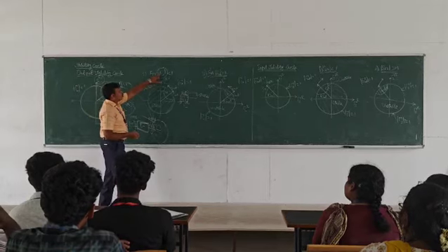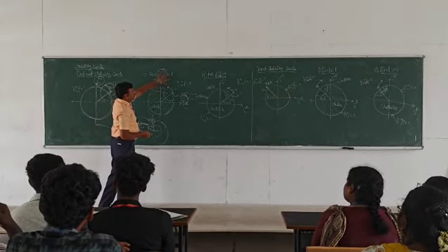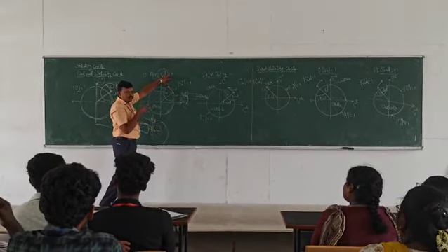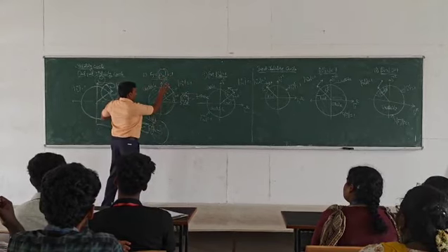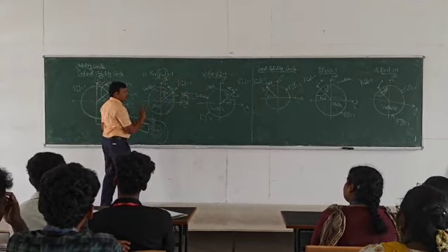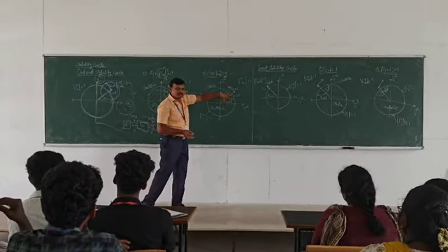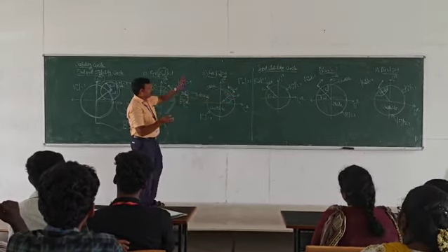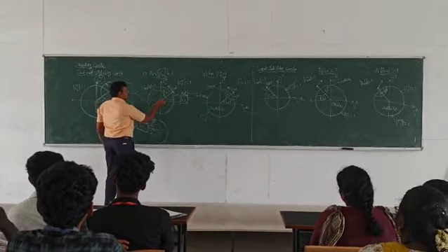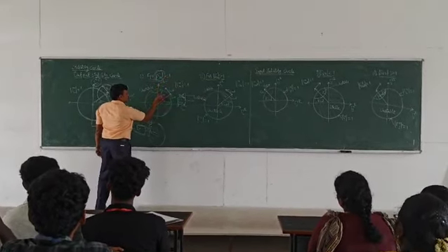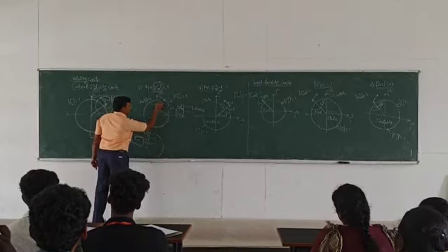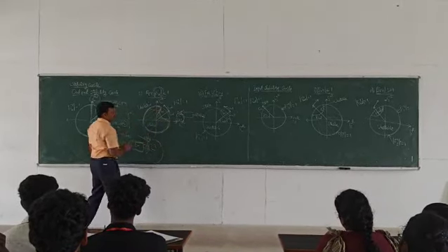Suppose the modulus of the reflection coefficient S11 is less than 1, then we represent this circle. If the modulus is greater than 1, we represent this same circle. The only difference between these two is this: when it is less than 1, this portion represents the stability of our amplifier.